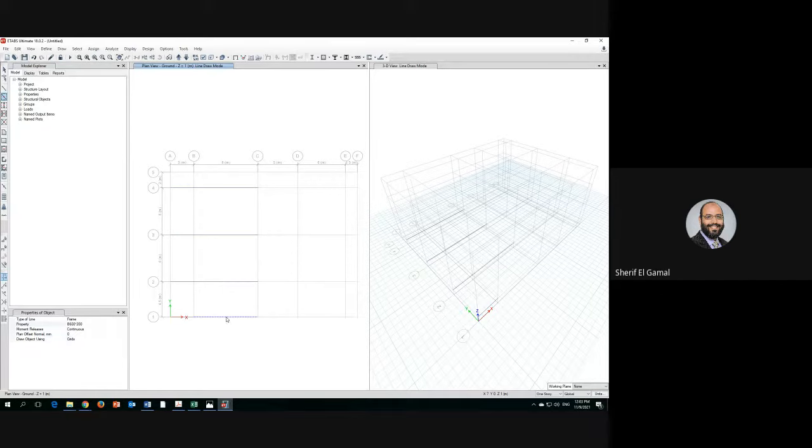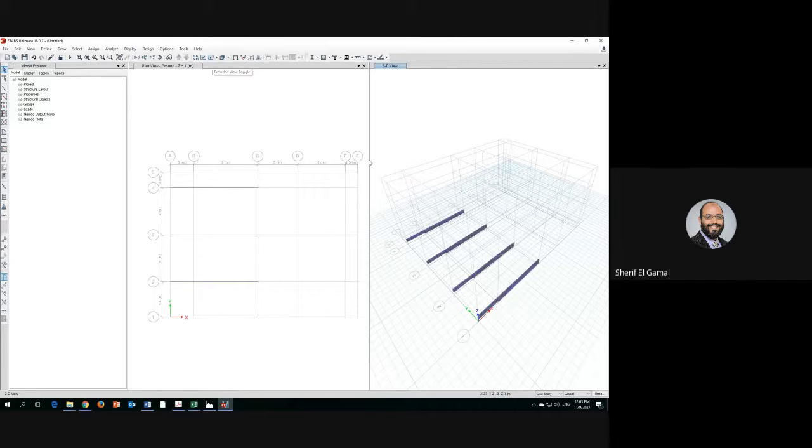And these are the beams. If you want to see these beams at real size, come here on this one. Because we were clicking on that one, it draws a beam here for us. Let's remove this beam, and we don't have anything. I will go to the top here and see something called extruded view. Click on this one. You can see now the beams at real size.